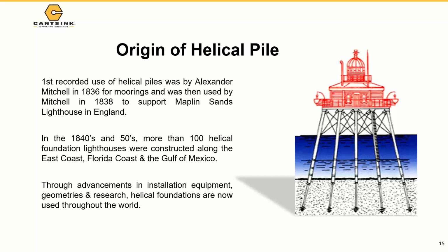I didn't have the big machine at that time at CTL Thompson, so I went to the Bureau of Reclamation in Denver, and I tested it. We tested about 10 of them. They went over 1.2 million pounds. I asked what they were using this for. They said this is for ExxonMobil, and they're going to install them somewhere in Canada. It's a 1-foot diameter shaft with a 48-inch helix. So nowadays, we have the machinery to install almost any shaft size.